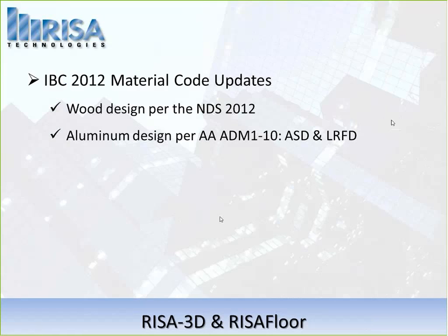If you're used to the aluminum design in 05, that was built off of the older codes. Aluminum and hot rolled are similar in their codes, and the 2010 aluminum code follows very closely the 13th or 14th edition of steel. It's a little different, but it combines ASD and LRFD nicely and is very easy to follow. In the 2010 code, you might see things like P-delta being required and adjusted stiffness methods, things you might be familiar with in hot rolled.